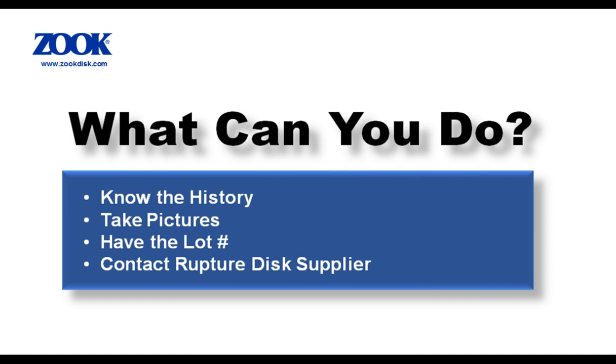What can you do? First of all, have the installation history at hand. Is this a new or existing installation? How long has a disc been installed? Have any of the process conditions changed? Valves, fittings, piping, etc. Have the problems begun with a recent shipment of product? Take pictures, plenty of pictures. The disc, holder, flange setup, upstream of the assembly, downstream, all valuable information in diagnosing problems and engineering solutions. Have the lot number of the disc at hand. All manufacturers use lot numbers to control batches of product. This is critical for fabrication investigative work.